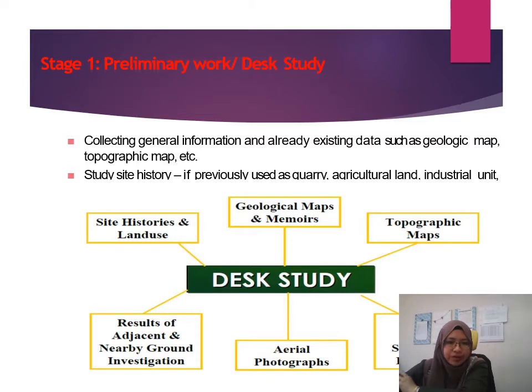So the site history, the land use, that is the history of the site, the geological map, the topographic map, results of adjacent nearby ground investigation. So if you have construction nearby, you can ask for the detailed site investigation, so you can relate it to your site.